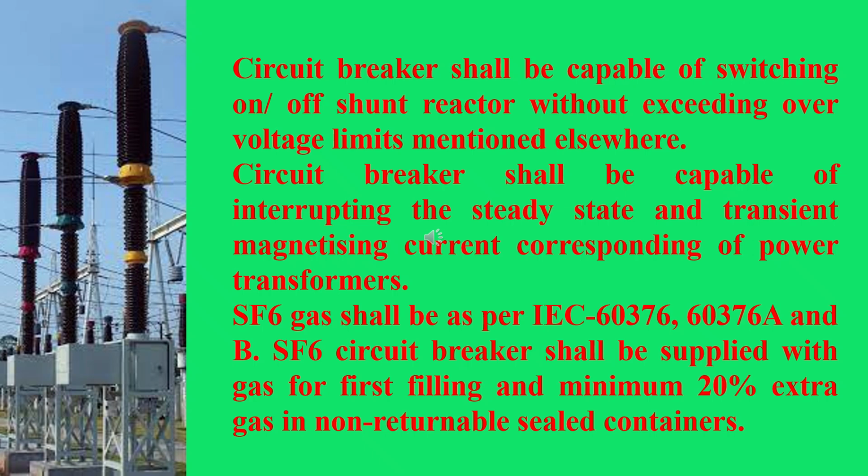SF6 gas shall be as per IEC 60376, 60376A and B. SF6 circuit breaker shall be supplied with gas for first filling and minimum 20% extra gas in non-returnable sealed containers.